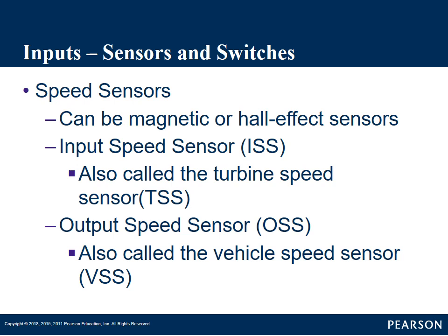If that engine RPM is one speed and the output speed sensor is another speed, then they can use logic to determine how much slip is in that transmission, in that torque converter, and determine whether it's slipping or not, and then set codes accordingly. If it has an input speed sensor and an output speed sensor, then to determine whether the torque converter is slipping or not, they monitor the input speed sensor and the engine RPM, and then they can get an exact amount of slippage.